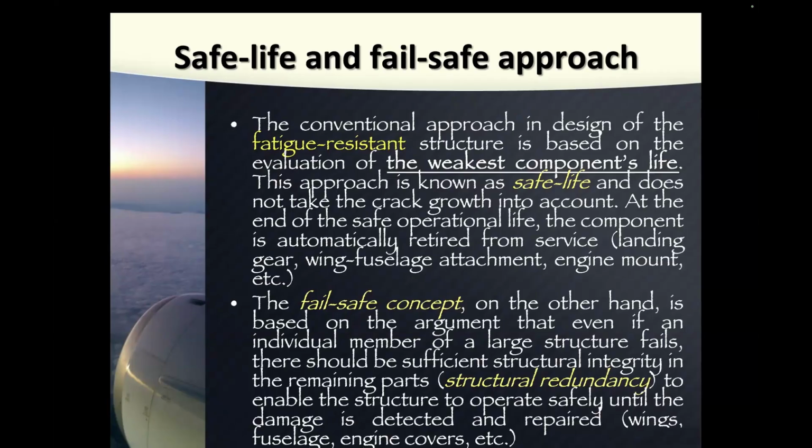So that is the engine mount that you can see on this slide. That's the part of the engine mount. The other approach is called fail-safe concept. In this case, we allow cracks to appear. Why? Because we have redundant structure.